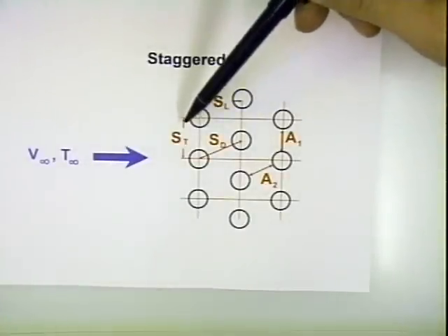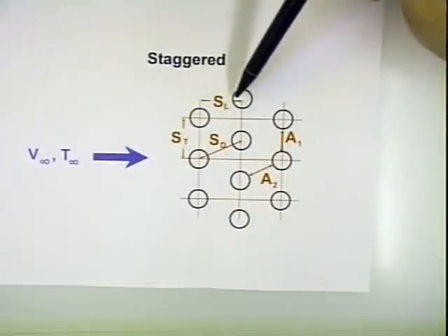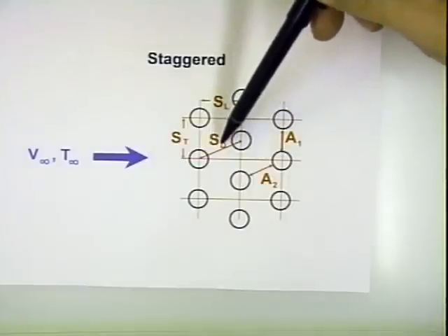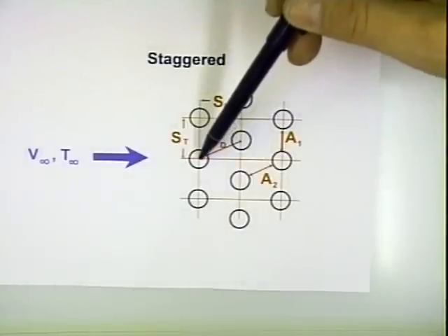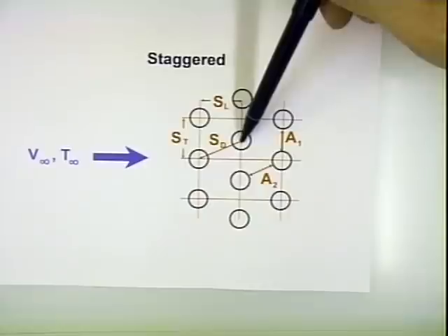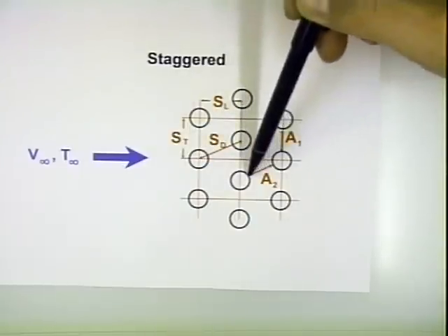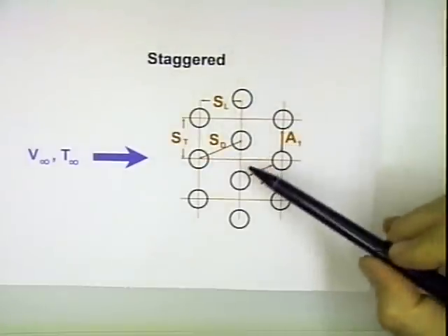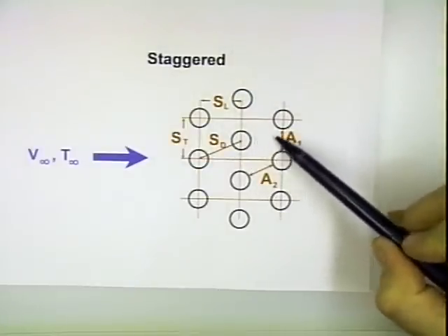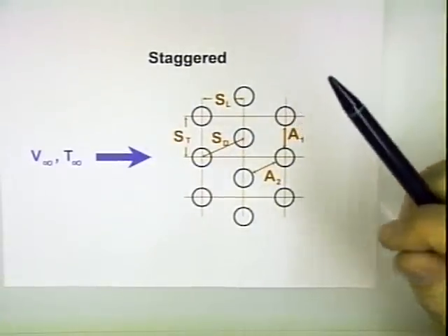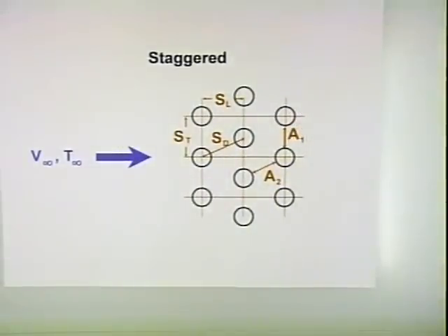We still have our transverse pitch, and we have our longitudinal pitch and our area, but I've added two additional dimensions. One is the diagonal pitch, the distance between the center lines of two tubes in different rows, and then we also have a second area. So the flow will be going through area 1, but it will also have to go through area 2, and that will make a difference in our calculations. Okay, so now that we have that, we can use that to calculate our Nusselt number.